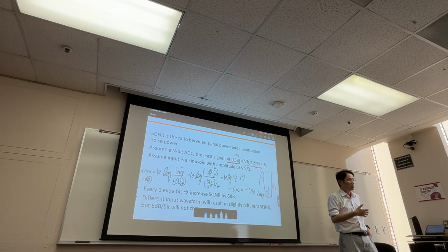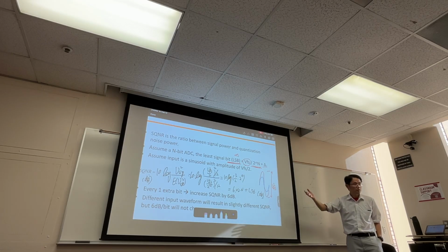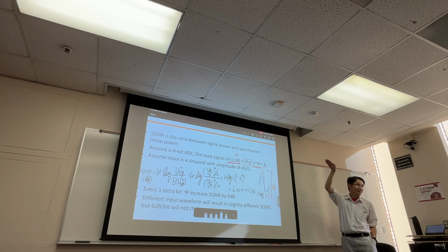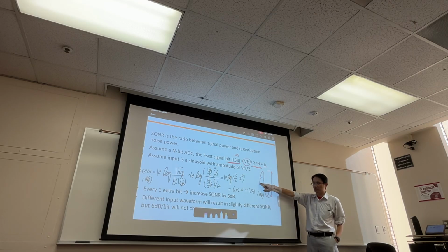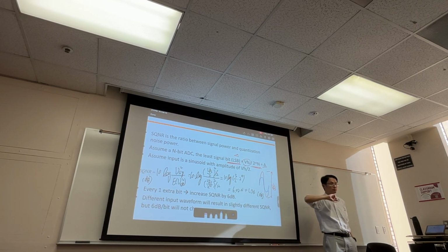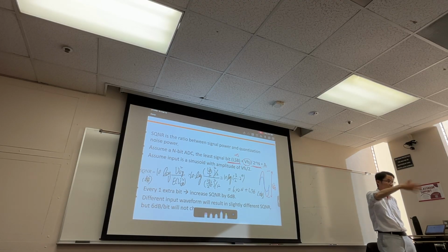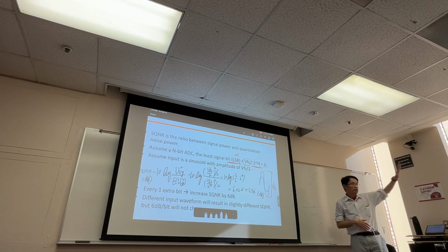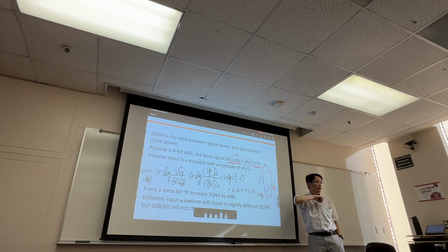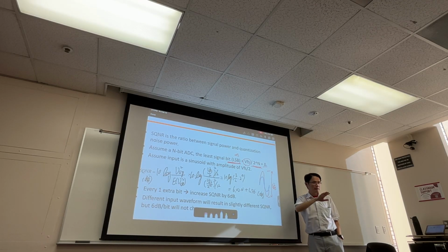Yeah, but like I said, when we define the SQNR, typically our common consensus is that we are exploring the maximum achievable SQNR. So it is still correct that you just assume that's a sine wave with a full swing, right? But just keep that in mind. In the future, if you're gonna use this ADC that you designed for a particular system, and whoever designed the previous block says, oh no, I'm sorry, I'm just gonna give you half of the full swing, then you have to make him or her understand, fine, if you're gonna do this, you're gonna waste.